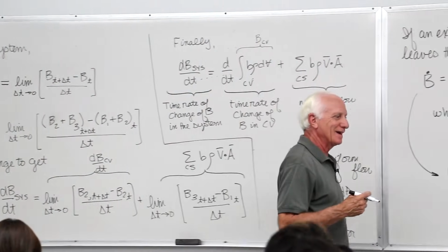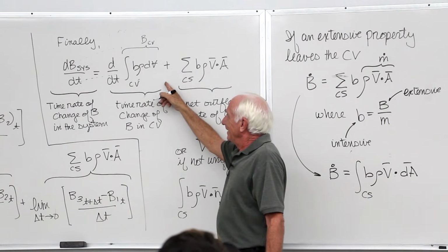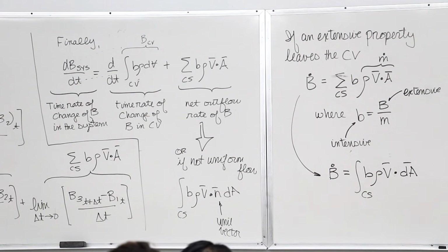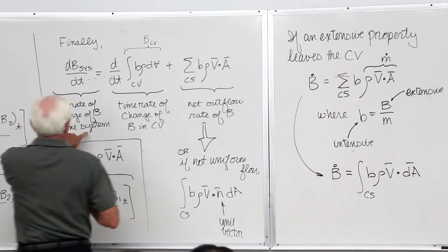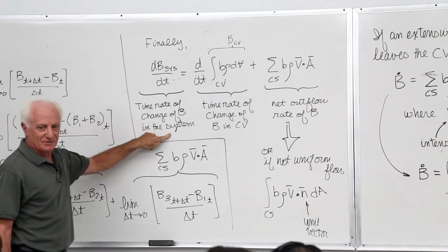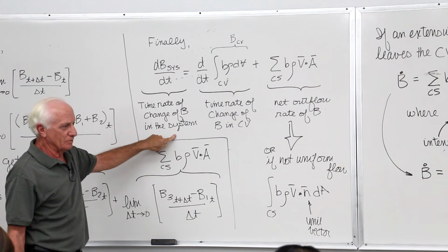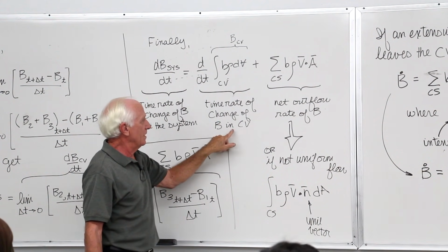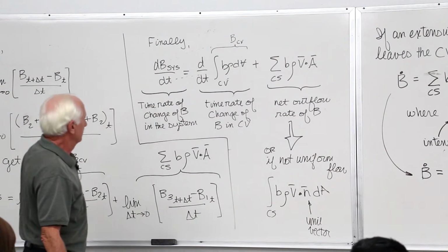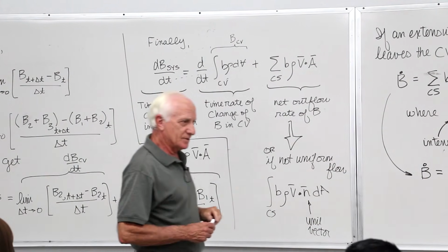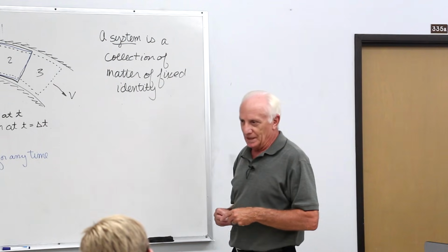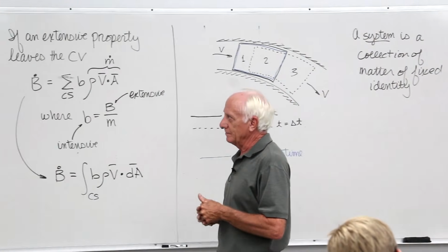I can't box it in, there's too much up there. That final equation right there, in symbolic terms and word terms, is the Reynolds transport theorem. What does it relate? On the left-hand side, it relates changes in the system, as the basic laws of science are generally expressed. We engineers want it expressed in control volume terms. So the right-hand side is the control volume terms. Control surface there, control volume here. If it's steady state, that term goes out. So that's what we're going to use for mass, momentum, and energy in Chapter 5. We'll let capital B be mass first, then momentum, and finally energy, and develop three equations from the Reynolds transport theorem.